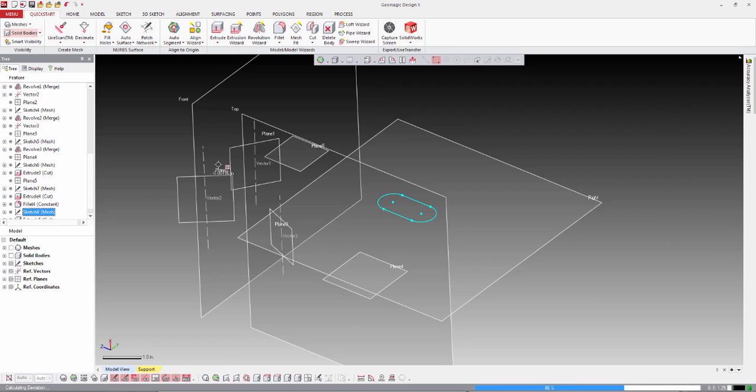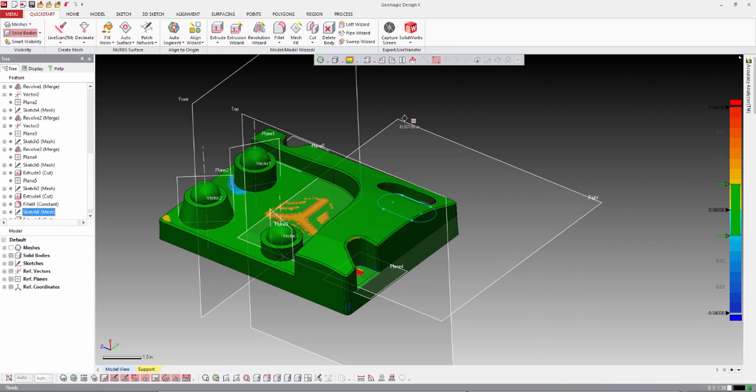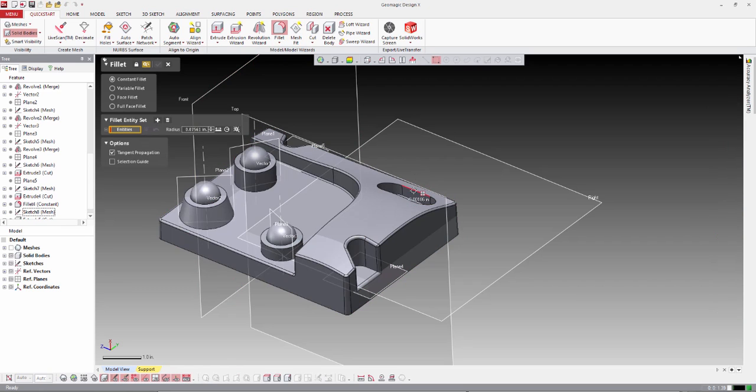And at this point, we'll see this geometry nearly completed. And the fillets, once again, to this edge. You can estimate the radius of the fillet based on the scan data, that's a smaller value. If I wanted to square this up to 0.020, I could do that now.